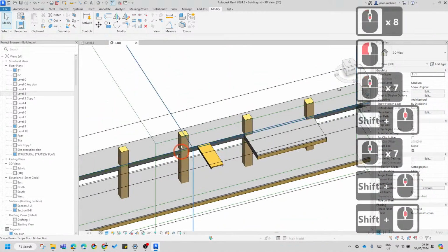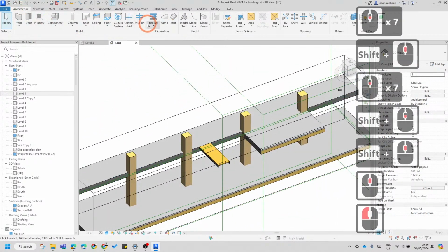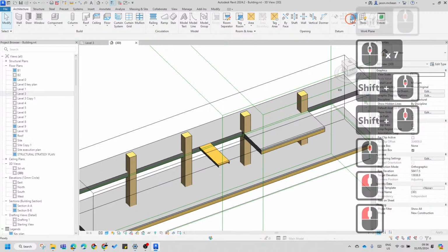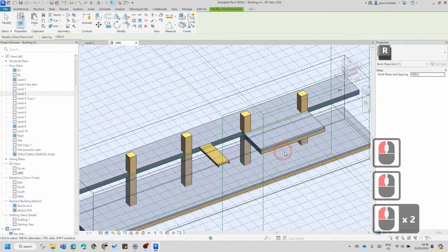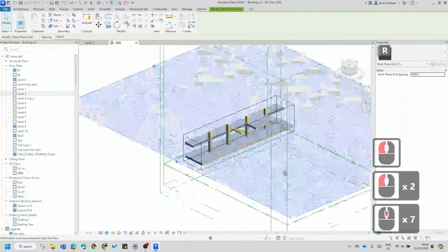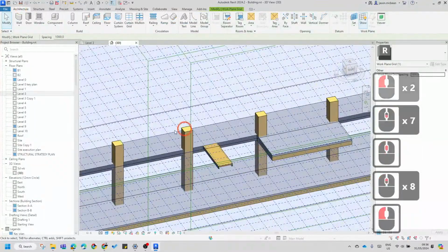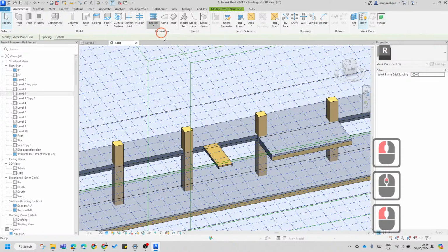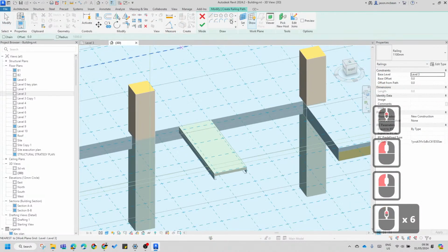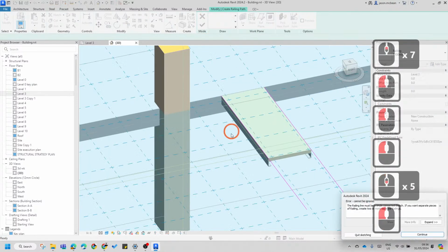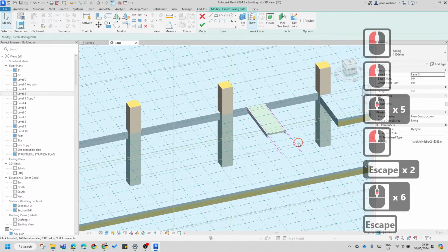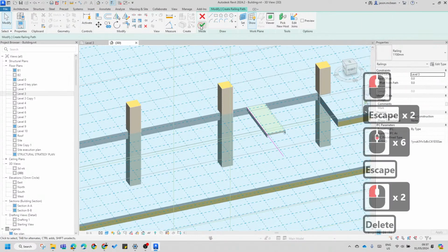Okay, now if I want to put a hand railing, so you get an architecture hand railing. Make sure level 3 is set, and say show work plane. Now you see it's showing me that's my work plane. I can actually do a lot of the modeling in 3D view sometimes. I switch between sketch path. So I'm going to say pick line, one there and one there. Oh yeah, you can only do one at a time. Otherwise, they have to be closed, finished.